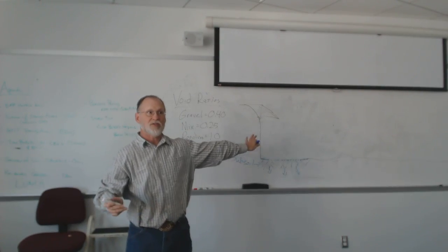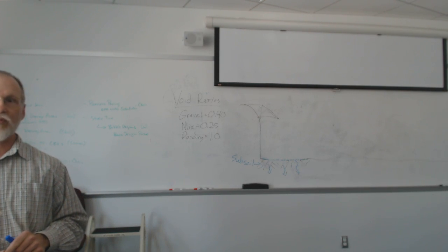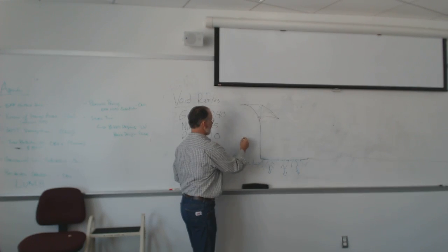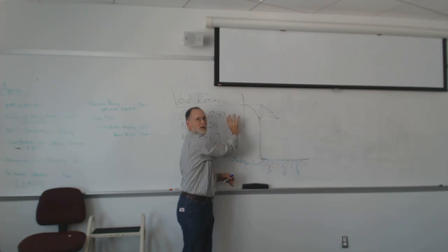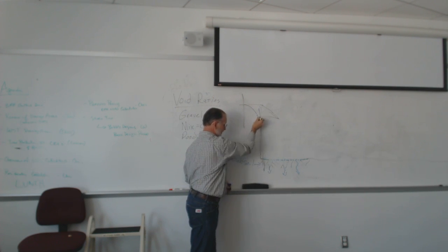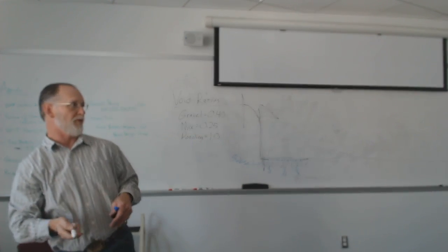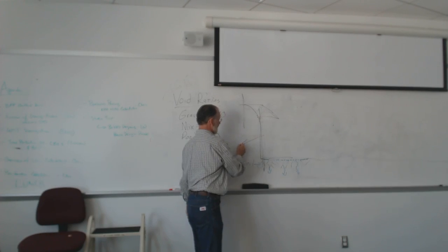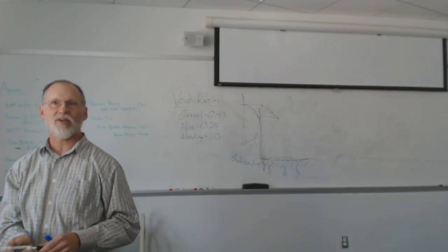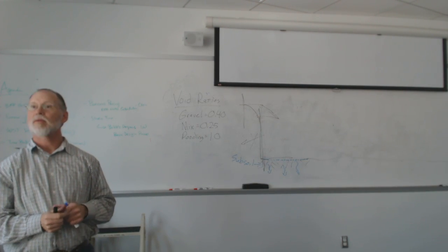But for all intents and purposes, all of our infiltration is really happening through the bottom, and we ignore the sides. In some cases, if we've got some kind of a construction over here or a building over here, I might actually take a piece of pond liner and intentionally run it down that side, maybe along the edge, to create an impermeable barrier so water can't get over here and screw up a structure. But that's kind of advanced rain garden stuff. But the sides are not that critical. The bottom is absolutely critical.